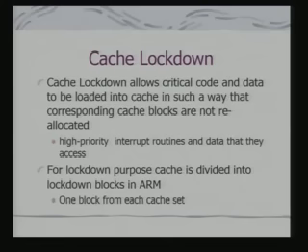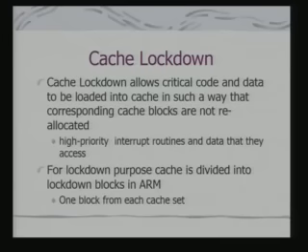Now, in case of ARM, they provide this similar facility for cache, because if I can do it in the cache, then some critical part can already be loaded onto the cache which would be repeatedly used. Okay. And for lockdown purpose, cache in ARM is divided into what we call lockdown blocks. So, one block from each cache set can be marked as a locked block.